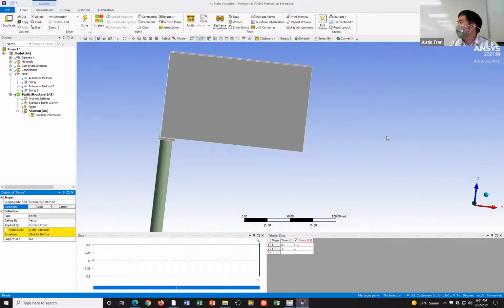in case you do want to apply a point force. Okay. All right. To apply a force at a point, you're going to go to this section of the bar, and make sure you're on point selector. Okay. And then you're going to move your mouse around the middle of the post, the middle of the sign, until you see it highlight a little bit.